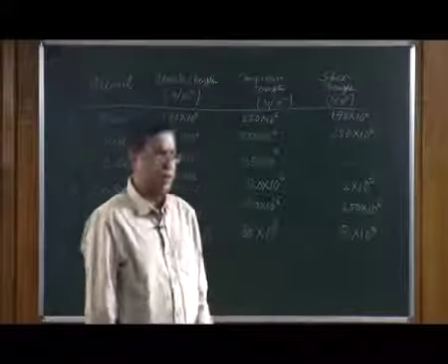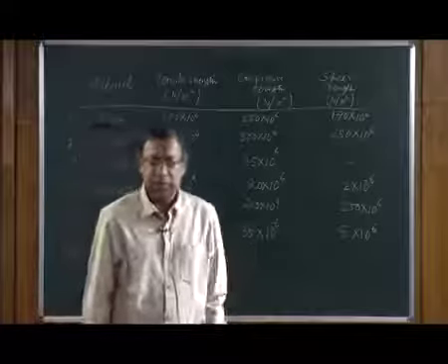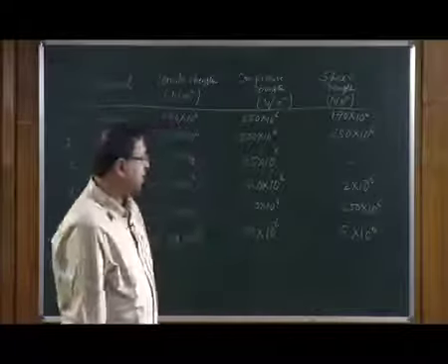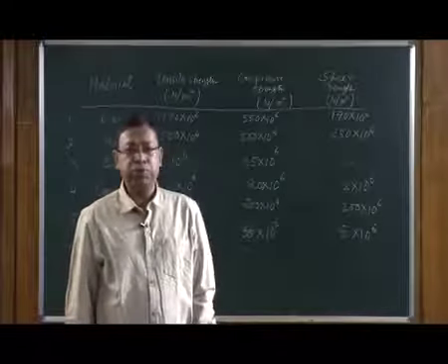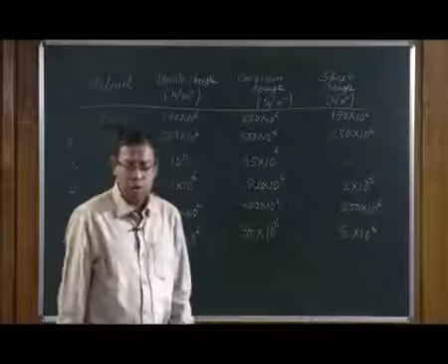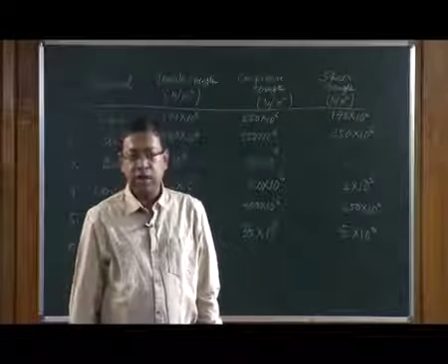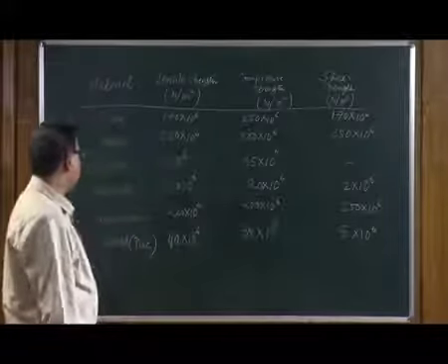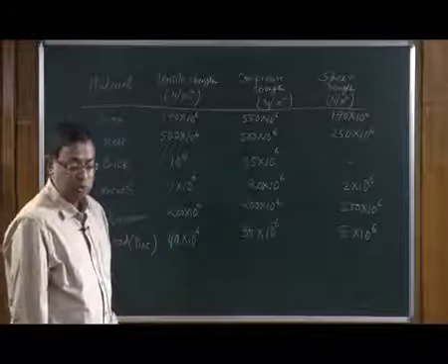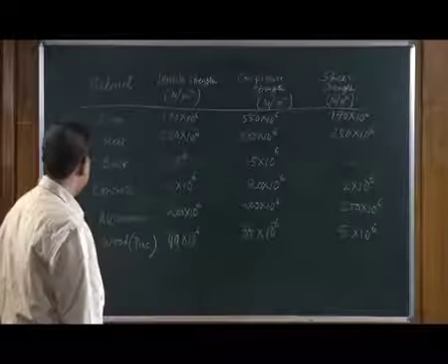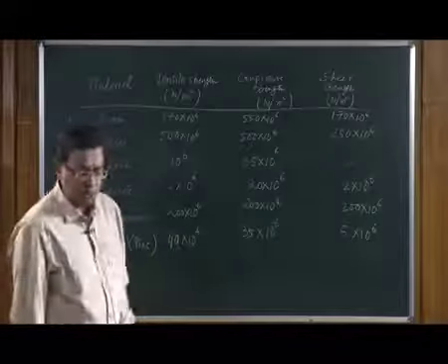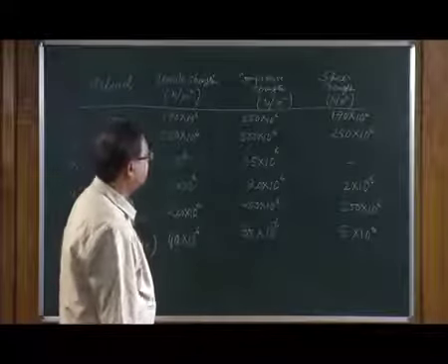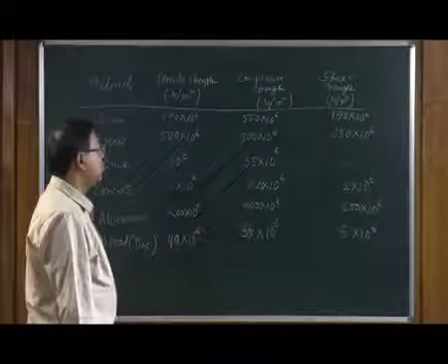So, we were talking about the strength of materials. I have listed some of the materials which are very familiar to us, and we have seen that if the stress on a certain object is too large, it will cause either permanent damage or it will cause fracture and make the material break. Some of these materials which are listed on the left are very familiar to all of you. They are used as building materials. They are iron, steel, brick, concrete, aluminum, wood, especially pine wood, and we have listed the maximum tensile strength, maximum compressive strength and maximum shear strength, all in Newton per meter square.